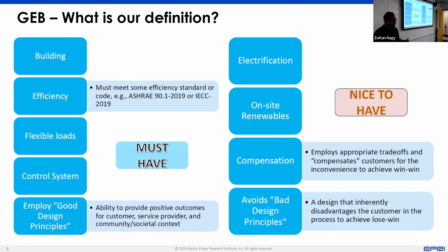The second thing is on-site renewables. Again, depending on where you are, it may or may not be the right environment. In California, for example, you are highly discouraged from putting on rooftop solar. Why? Because you have an overabundance of solar energy in the middle of the day when the loads are low. When the solar turns off and you come back home and turn on your air conditioners or plug in your electric vehicles, there is no solar, and you now have a huge gradient between where you are and where you need to be. That ramping requires a lot of peak power plants to be kicking in, so the carbon emissions at that time are very high. So if your goal is to decarbonize, on-site renewables with solar in California is not the right approach.